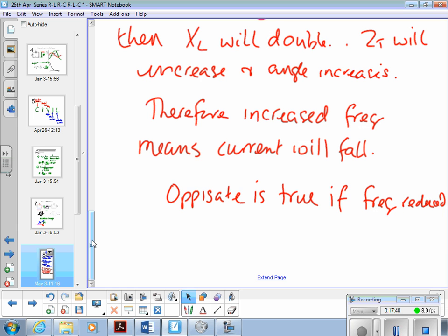It's really important to understand those underlying principles. It really helps with the maths. When I make a change to the circuit, you can think, does my calculation look right according to the principles of what's changed? And we're talking here about changing frequency. We haven't changed any value in the circuit. All we've done is change the frequency of the supply, and the conditions change if there are reactive components involved, in this case, an inductor.